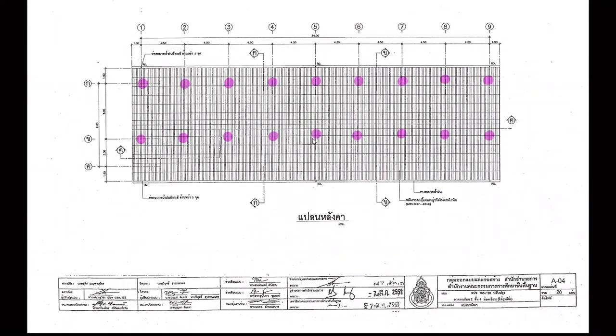So that means the roof system around here from grid number 3 to 7, you need to try to find a way to support the roof system. And since you must find a way to support the roof here with just these columns anyway, that means you can use the same system for the area around here where you can actually have columns coming up from the grid, right? So in fact, you don't need it. So that means we are going to try to provide the truss system.